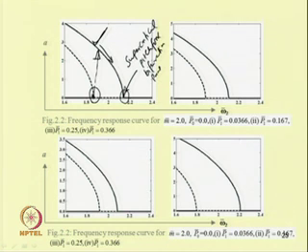So, depending on the initial condition, that is, depending on the frequency of excitation and amplitude of excitation, the system response will be different. So, one can, while sweeping down the frequency, similarly follow. Up to the supercritical pitchfork bifurcation point, the system will be in its trivial state, and after that the system will have a non-trivial state. That means the system will vibrate at an amplitude equivalent to the response amplitude of the non-trivial state.